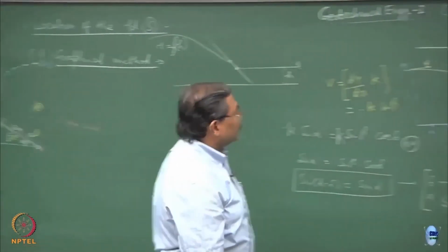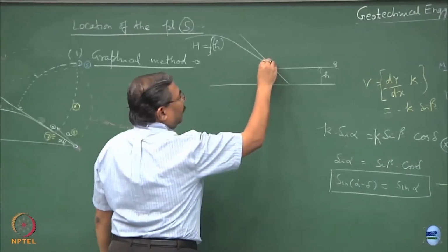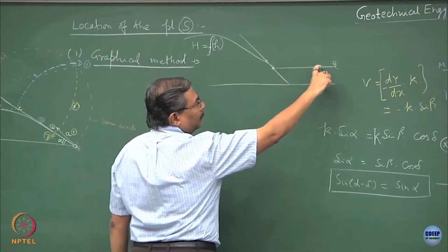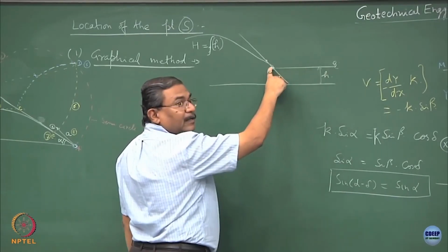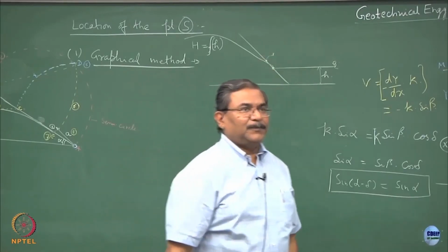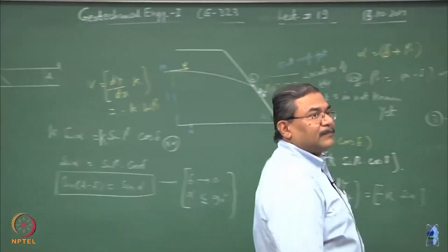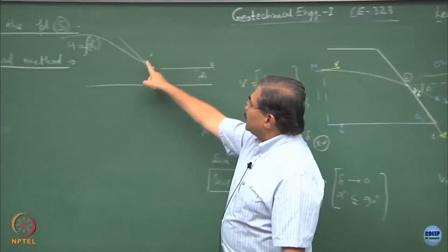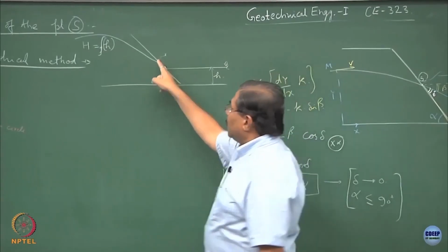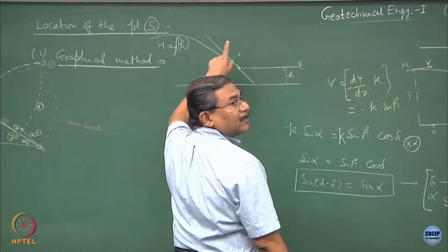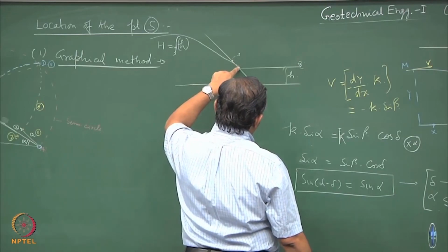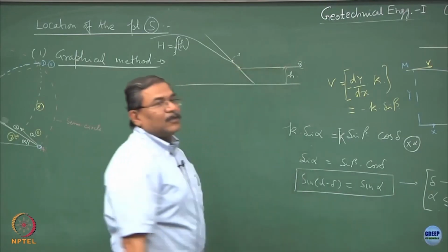Please realize this. Very conveniently, what I did is, by assuming this point over here, I have imposed this condition of H at this point. At this point, unfortunately, you do not have H valid. Are you getting this point? Because this happens to be a discharge point, this is not a seepage point. That is what we have proven. So, in order to get a mathematical solution, we have forced this point to be lying with the top tail water, so that we can obtain a solution.